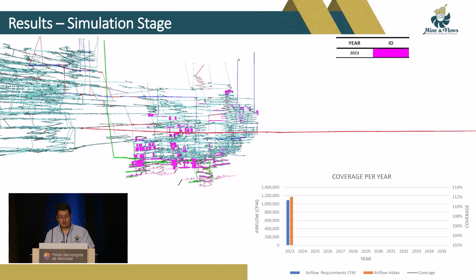Lastly, the stage tool in Ventsim was one of the most useful resources when evaluating the medium and long-term ventilation design. For this, the construction of the model must consider an adequate integration between stages, making them depend on each other, so that anything modified in early stages must be reflected in the following stages in case it is required.